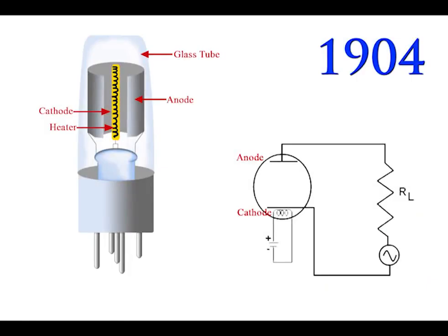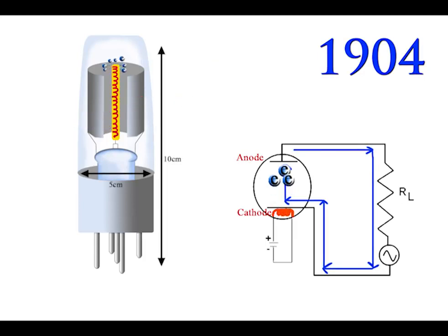The vacuum tube diode is a device which consists of a sealed glass tube that could control electric current between the electrodes through thermionic emission. The anode plate then attracts those electrons emitted from the heated cathode plate. This creates a flow of electrons, also known as current flow, and completes the circuit. However, because the anode plate wasn't heated, electrons could not flow in reverse direction.